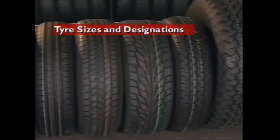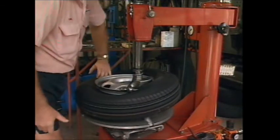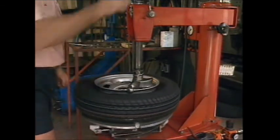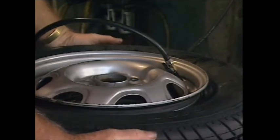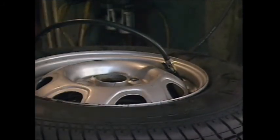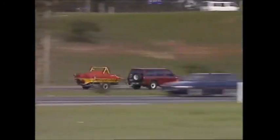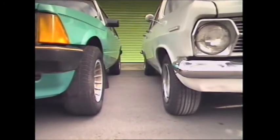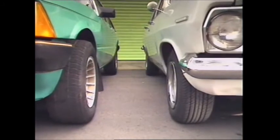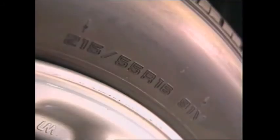This section examines tyre sizes and designations. The size of a tyre must satisfy some basic conditions. The bead diameter must suit the wheel rim diameter. Section width must be suitable for use on the wheel rim and large enough to have a suitable load carrying capacity for the vehicle. The overall tyre size must allow sufficient clearance between the tyre and the vehicle frame. All manufacturers mould information about the tyre into its sidewall.